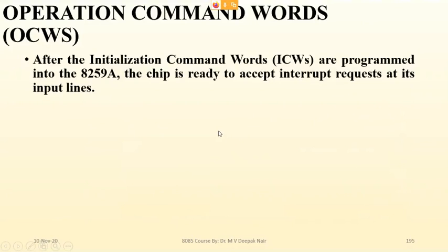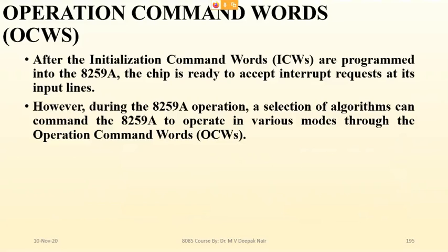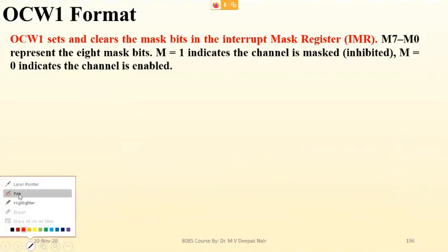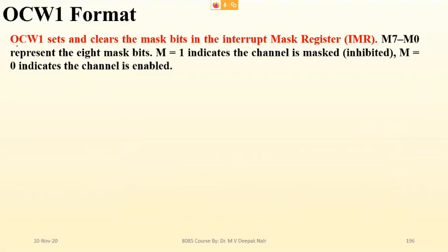Okay, so operational command words. Remember there are three operational command words. Now let us talk about the first operational command word, OCW1. OCW1 directly tells you which of the interrupts are being masked.